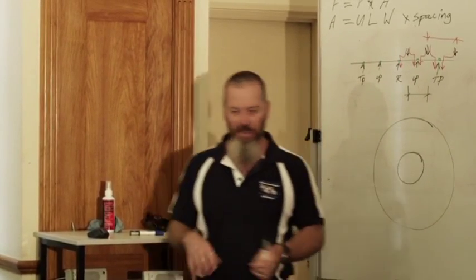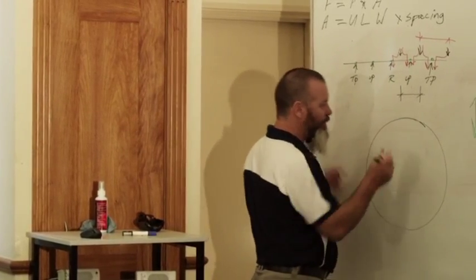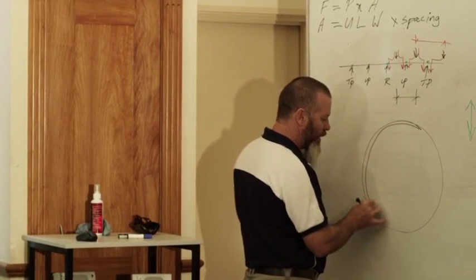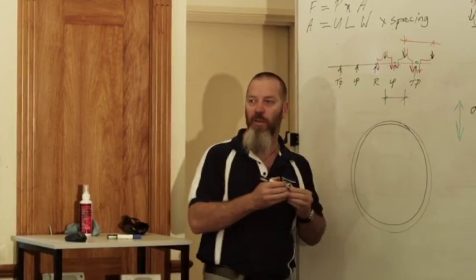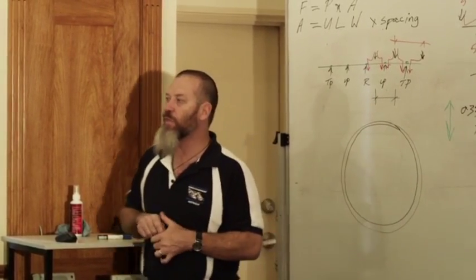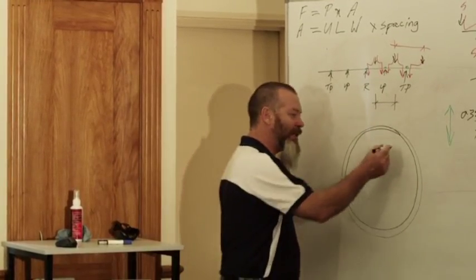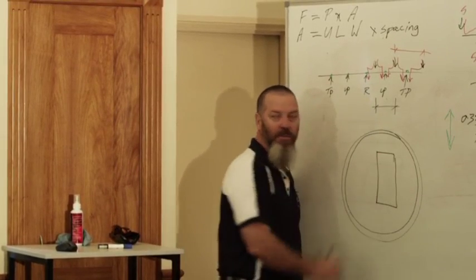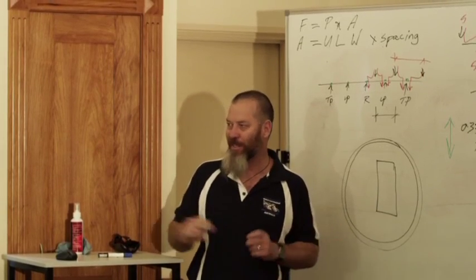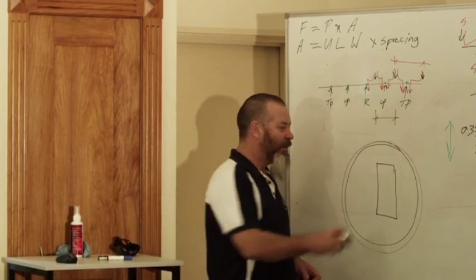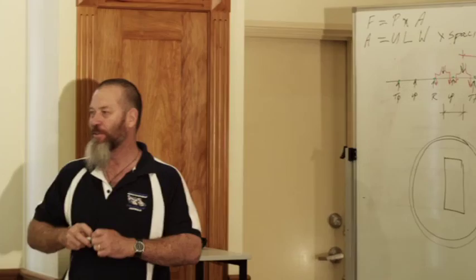So it's only about 20% of the section size of the timber. But a piece of hardwood has a sapwood about that big. So the moment when you get a piece of treated hardwood, the treated hardwood is what we call an envelope treatment. It's just basically a treatment that goes around the outside of it, because it's likely that the piece of hardwood that you're using comes from there, which is all heartwood, which doesn't accept treatment. So providing you don't cut that piece of hardwood, your treatment's all good.